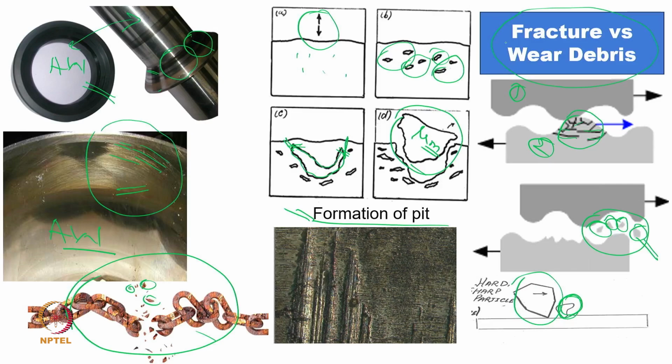So, that is why we say the main aim of this lecture is to think of the wear debris as a smaller division, maybe a micron level or nano level division, of the fracture itself, and we should take precautions and analyze it. When we think about SEM, we need to make a sample, and the chip with the wear debris itself is of a smaller size. We can really make an easy sample with that. If we need to look at the grain structure, whatever etching mechanism is needed, that also can be done on this kind of debris.